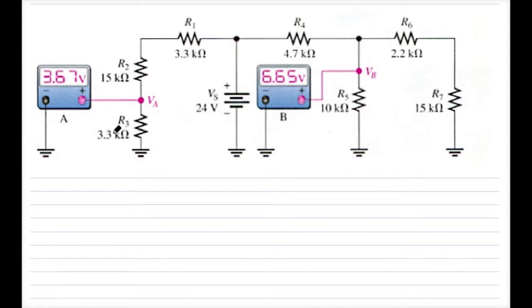All right, so you can see in this circuit we have 3.3K with 3.3K, 6.6K with 15K, that is then 21.6K, and then we've got 3.3K, across which the voltage is taken. If we run the maths on the calculator, 3.3, no need to put K because it's all in K, divided by 21.6, 0.152.